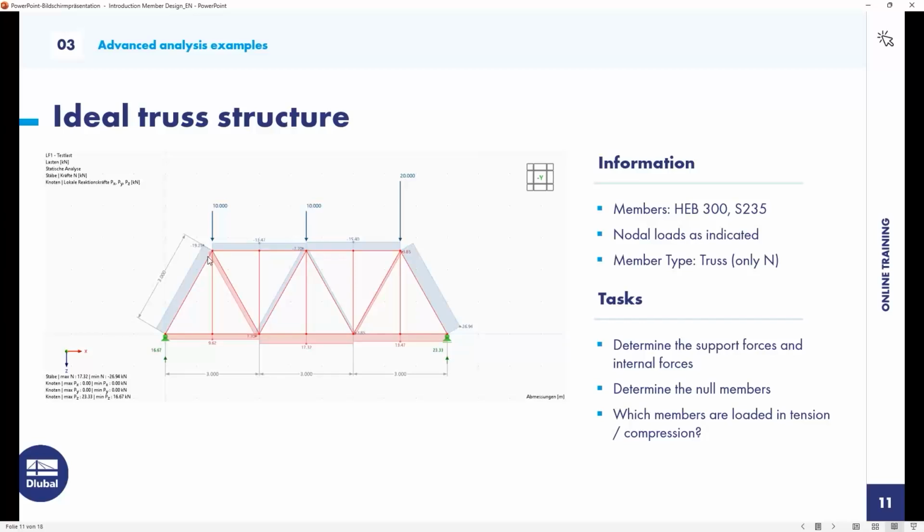So that means that there are no bending moments which can go from one member to another. Also, it is important that all members are straight. Yes, that's definitely fulfilled. And there cannot be any imperfections, and as well, there cannot be eccentricities. So we don't have this in the system, so that would be fulfilled.